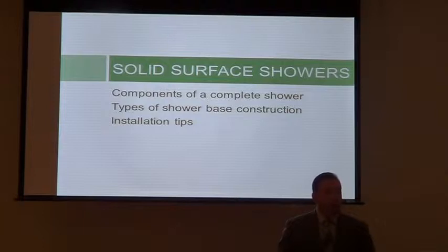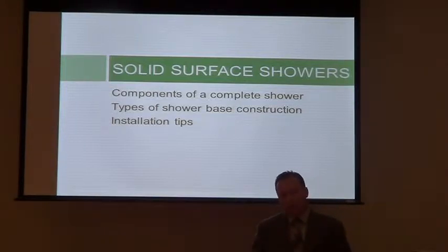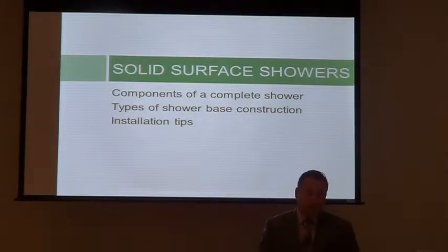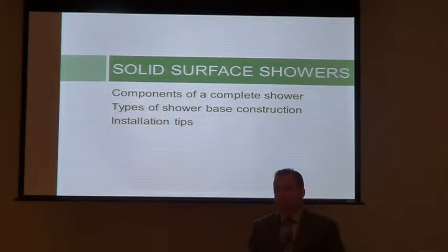If it's a chip or a repair, there's typically two solutions. Most manufacturers will rely on their local fabricators to use glue. And there's a variety of tricks of the trade. Far too many to get into great detail right now, but you can actually do what's called a drill and fill. It's not like having a cavity in your tooth. Kind of drill up the problem area, fill it back in, allow it to get hard, sand it smooth. That's the easiest way to fix like a void or a chip of some sort.